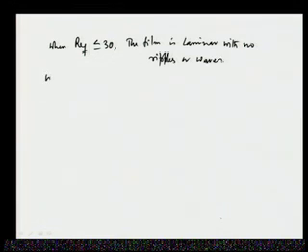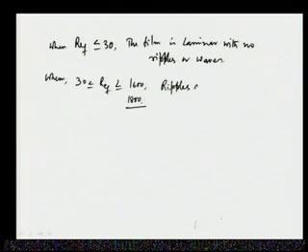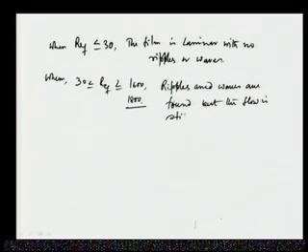Now, when 30 is less than or equal to Re_F less than or equal to 1600, sometimes it is written as 1800, in that situation ripples and waves are found, but the flow is still laminar.